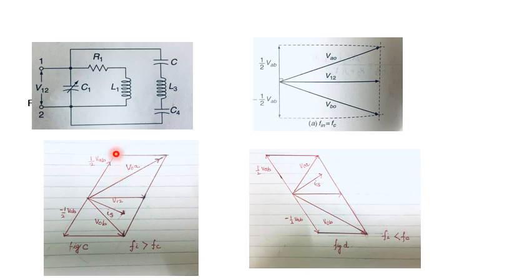But the voltage VAB, this is the secondary voltage. The secondary voltage is produced by the secondary current Is passing through the inductor coil. Therefore, the voltage VAB across the secondary coil leads the secondary current Is by 90 degrees.